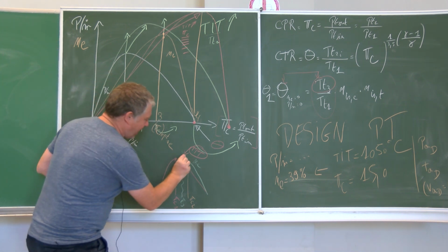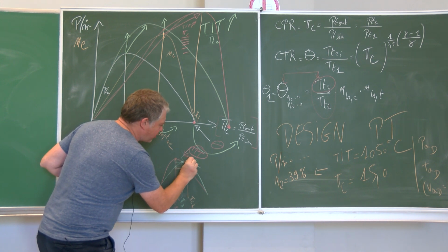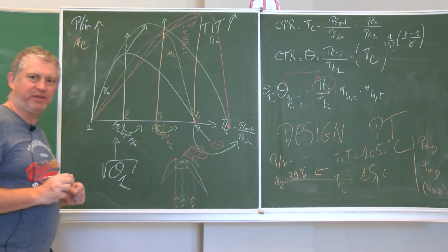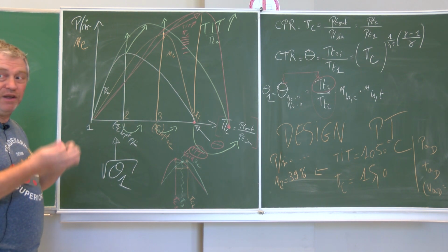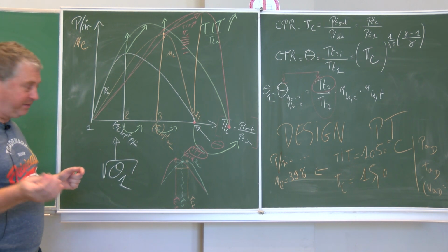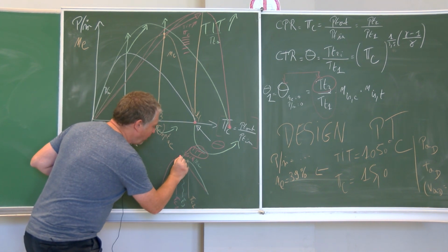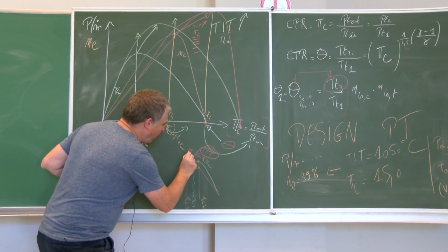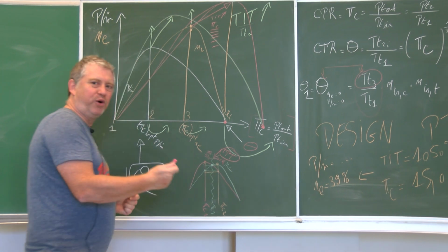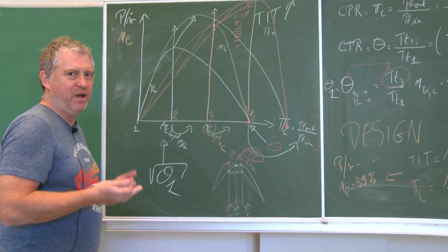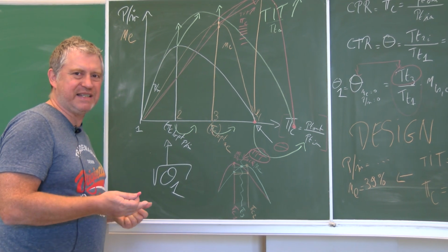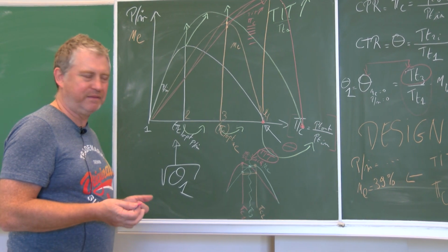If you have long-range aircraft, a bit more to the right, because you are burning fuel during a much longer time, and if you have a medium range or a short range, a bit more to the left, because you are burning less fuel, and so the fuel is becoming less and less important compared to the weight.